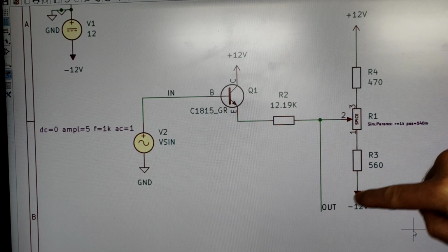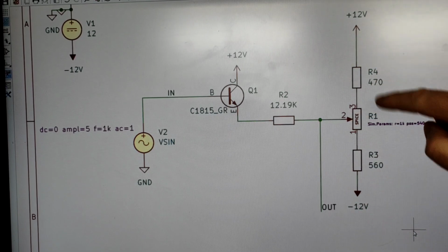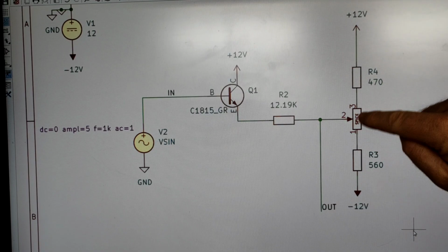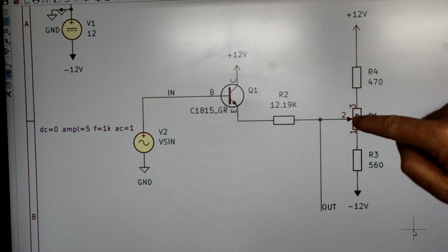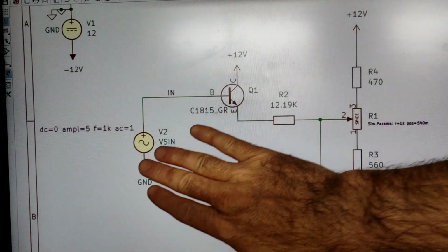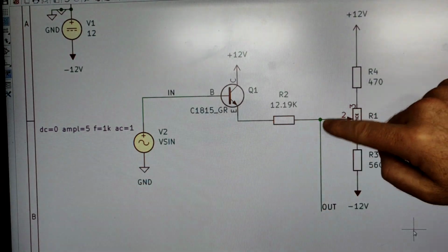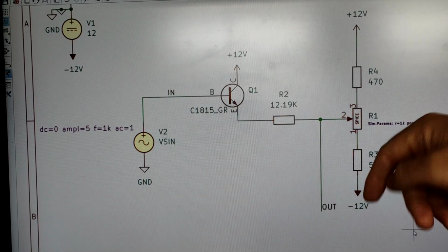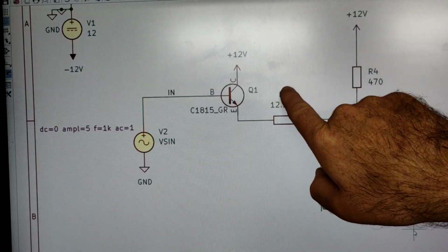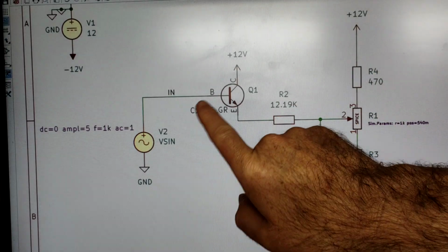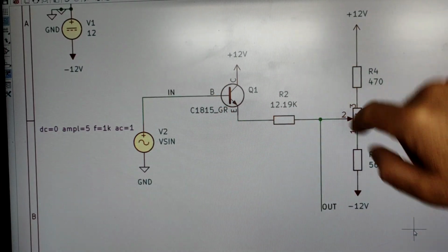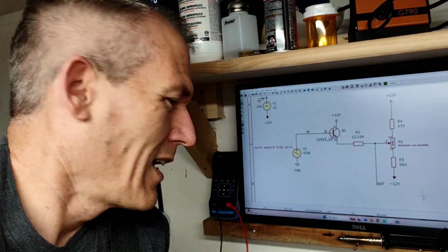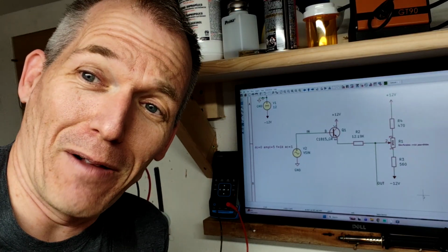And so on the right side here, we have a simple voltage divider. I put a couple of constant resistors here and a pot that I can trim here to get basically the offset. So moving this up and down has nothing to do with the input voltage, right? It's just going to change the voltage here to move it, net up and down. And then this one here, the ratio of this to this side over here determines how much impact this has on that. Now, I thought that this was going to work, but there's a really fundamental problem here.